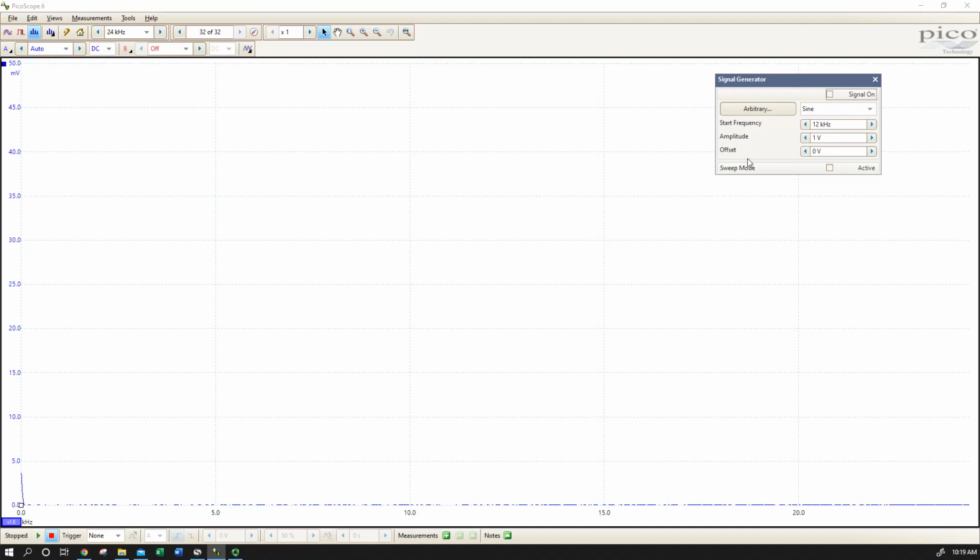So now we're going to look at something we probably haven't seen in the past, and that's sweep mode. So we're going to click active. Yes, we'd like to sweep. And I'm going to say I want to sweep up and down. So I want to start at some frequency below resonance, sweep through the resonance frequency to something that's about the same number of hertz or kilohertz to the other side of resonance, and then come back. And then just keep going back and forth. And I'm going to let my peak hold feature continue to gather the highest value each time I go through.